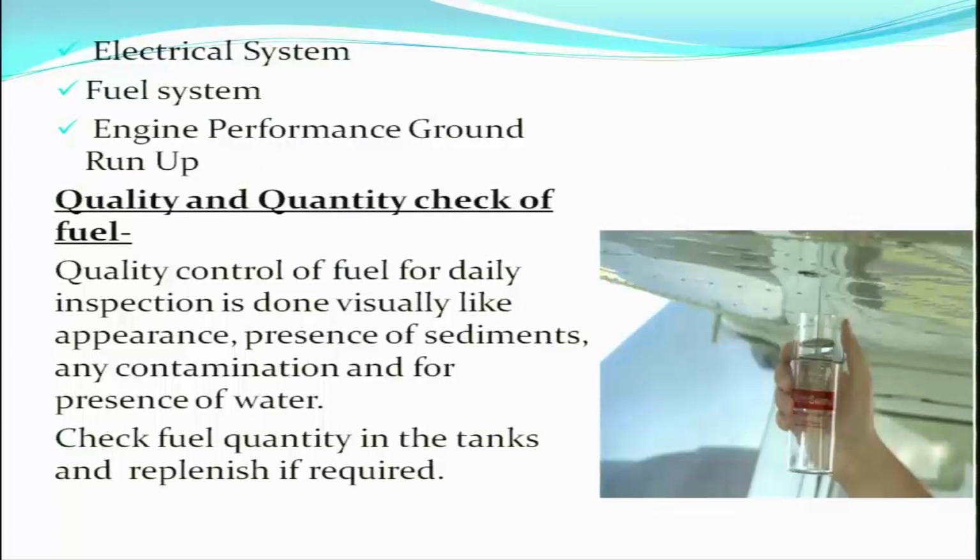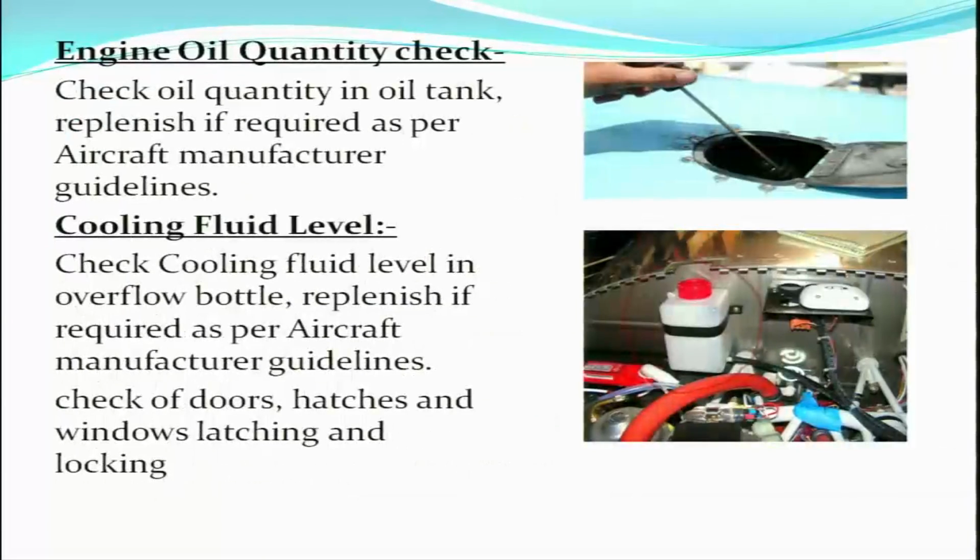Check fuel quantity in the tanks and replenish if required. In case your fuel quantity is less, then you have to replenish your fuel tanks. So, you need to check whether you have sufficient fuel quantity for the intended flight. Engine oil quantity check. In the figure you can see there is a dipstick. The oil quantity is checked with the help of this dipstick. Check oil quantity in the oil tank and replenish if required as per the manufacturer's guidelines.